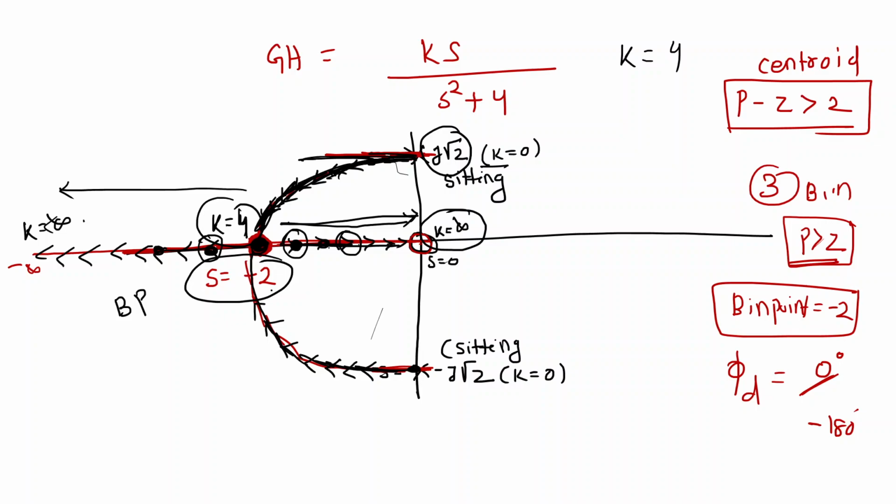So in that whole range, tell me what is the k value? K value is 4 to infinity, here also 4 to infinity, right? When k value is from 4 to infinity, you are moving on the right hand side. Also, I am moving in the left hand side. So now this is overdamped, right? Clear, sir.